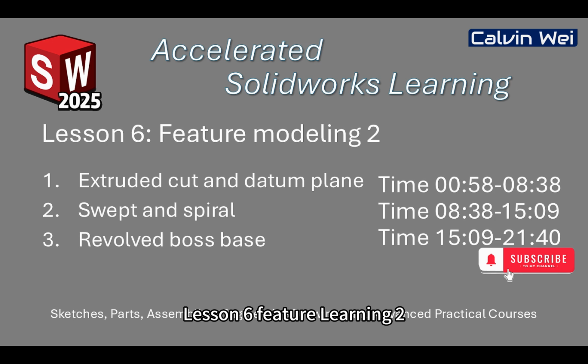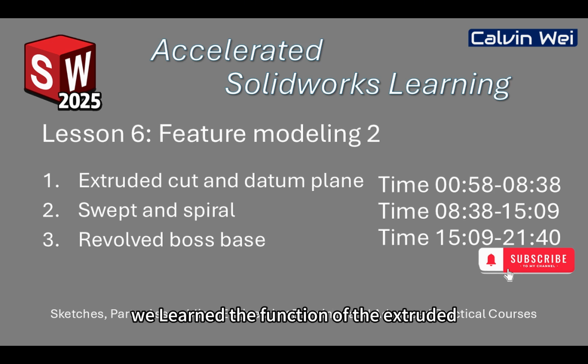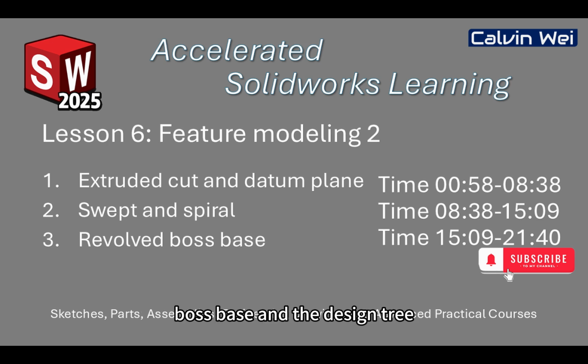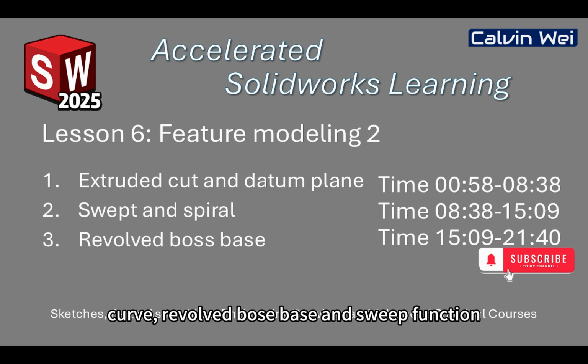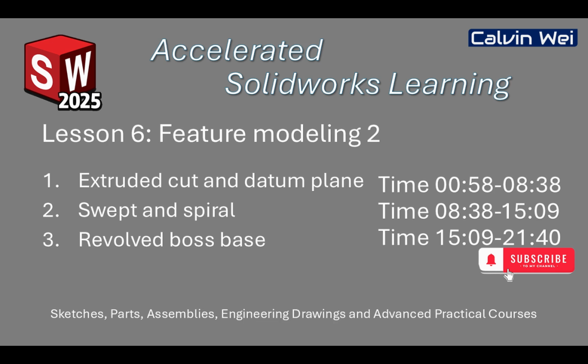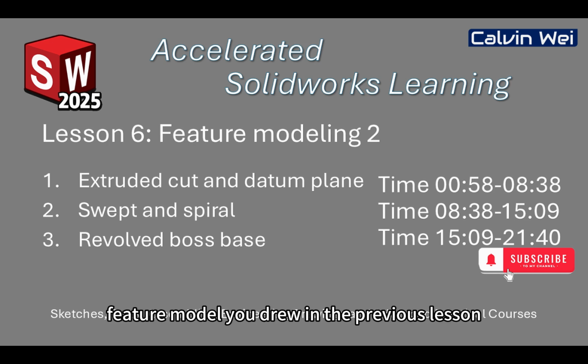Lesson 6, Feature Learning 2. In the previous lesson, we learned the function of the extruded boss base and the design tree. In this lesson, we will learn about extruded cut, reference geometry, curve, revolve, boss base, and sweep function. Let's start by opening the part feature model you drew in the previous lesson.